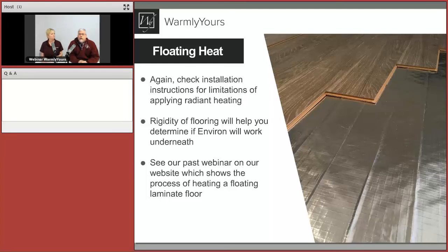It's very important that when you put this in and you're looking for a laminate or something like that, the ideal thing, once again, is to see if your laminate has a pre-attached foam pad underneath. Good point. Because a pre-attached foam pad or pre-attached cork will increase the R value once again, and we want to make sure that laminate product has no R value over 1.